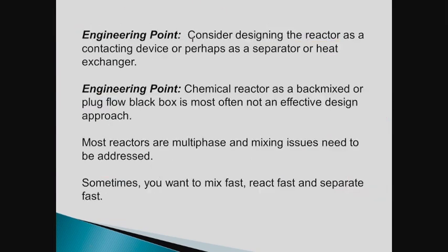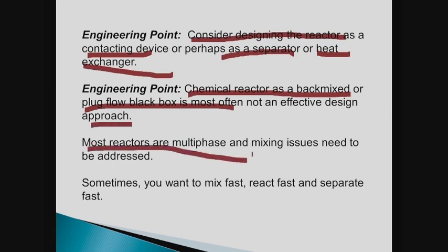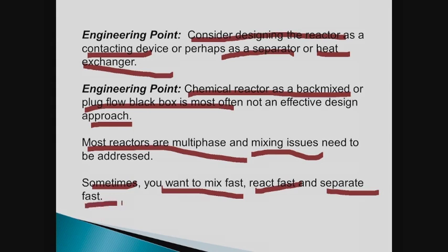Consider designing the reactor as a contacting device, perhaps a separator, perhaps a heat exchanger. A back-mixed reactor or plug flow reactor is most often not an effective design. Again, as I said, most reactors are multi-phase and mixing issues need to be addressed. Sometimes you want to mix fast, react fast, and separate fast.